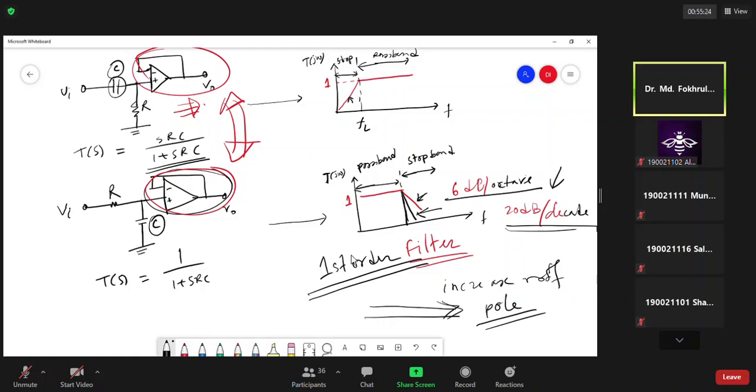Then you also need to know that the input terminals of the operational amplifier, the small V1 and V2, are always equal voltage. Also there will be no current entering the op amp. I mean the entering current of the operational amplifier is always 0, because we consider that the input impedance of the operational amplifier is infinite.